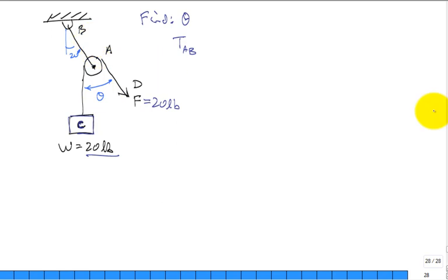All right, what are we going to do? How are we going to analyze this problem? Statics. The refrain in statics is get a free-body diagram, which is going to reveal how these unknowns are interrelated when you do the equilibrium equation. So you're going to do it up here around B? No, you've got to cut through the ceiling. You already did it around the weight, so let's do it around the only thing that makes sense, which is our pulley. So if we do a free body diagram, I know it's a point diagram, around our pulley at A,